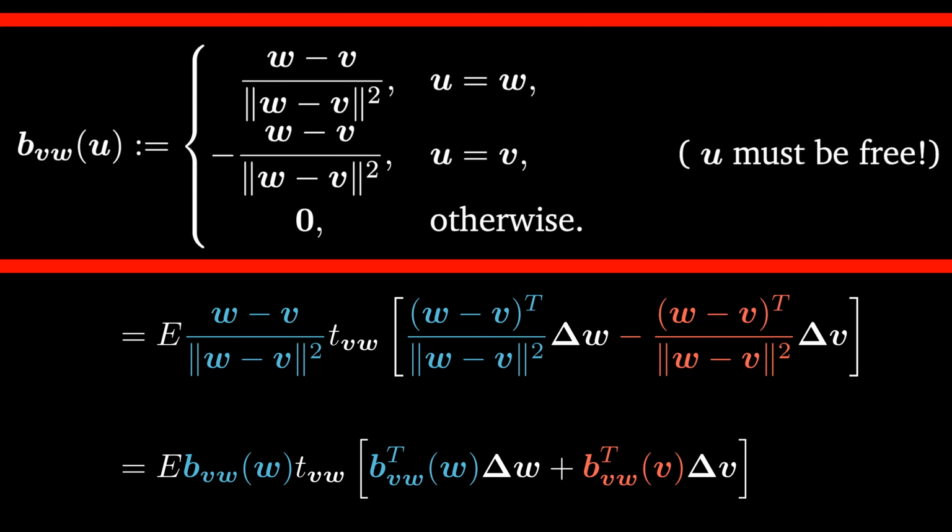This vector has always 2 times k entries, where k is the amount of free nodes in the truss. Nearly all entries in a row of this vector will be 0 except those entries that are in rows corresponding to the nodes V and W if V and W are free nodes. For the case that V and W are both fixed nodes, then this vector will only contain zeros.